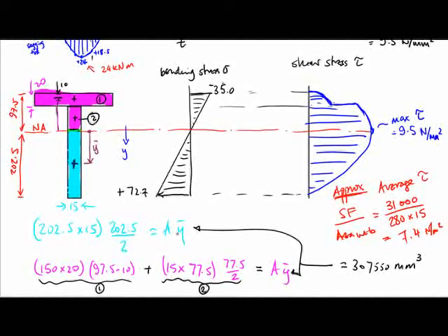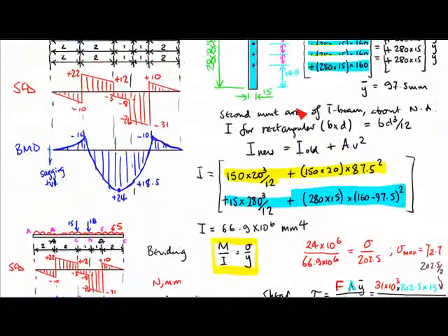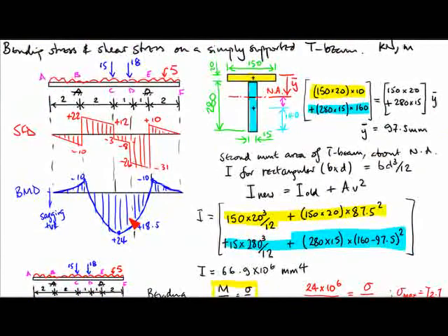So obviously, because it doesn't matter which way you look, you go for the simpler calculation. Okay, that then is an example of a beam with some loading, where they're giving us shear force and bending moment, and then from the shear force we get the shear stress, and from the bending moment we get the bending stress.